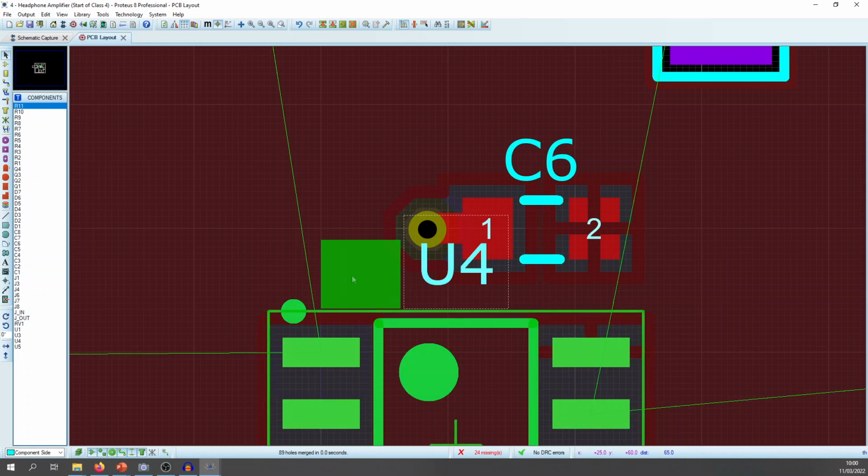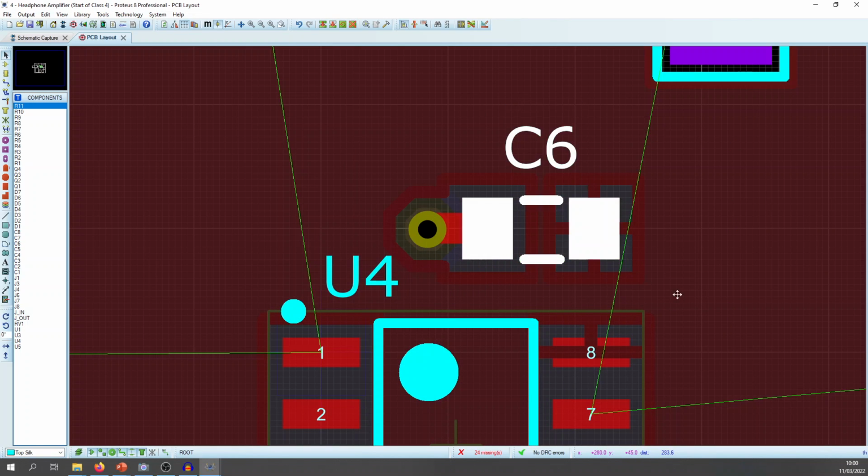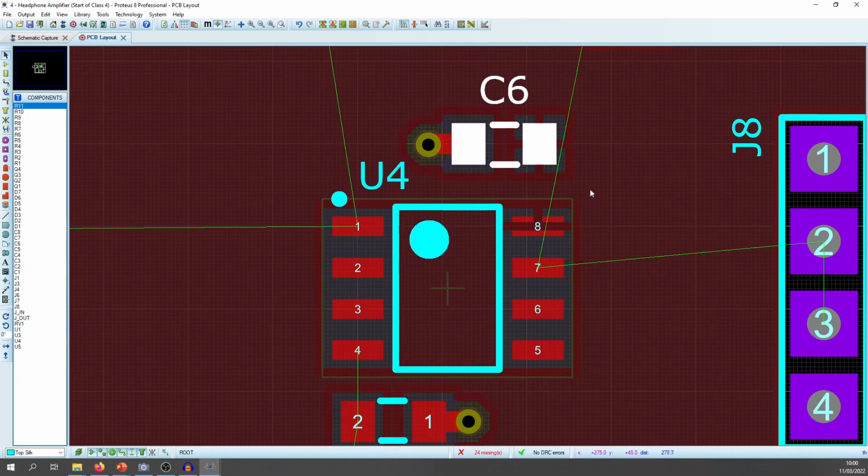Always make sure your reference designators are not getting overrun by stuff. This is another slightly confusing concept. Our top layer is plus 12 volts. This decoupling cap is plus 12 volts, that pin's plus 12 volts. So you've actually already got a connection between those 2 points.